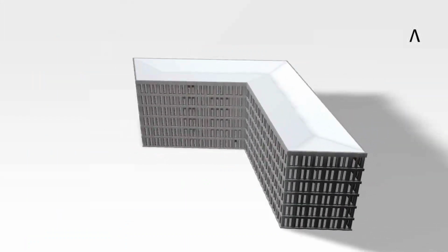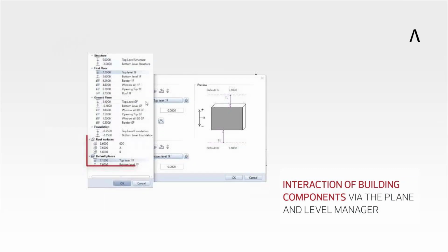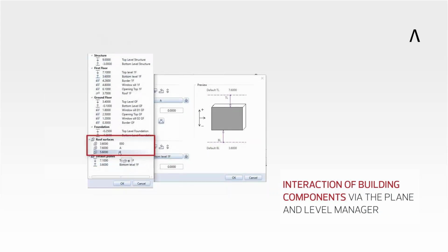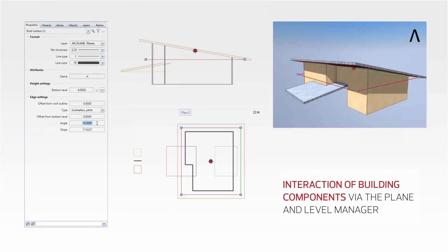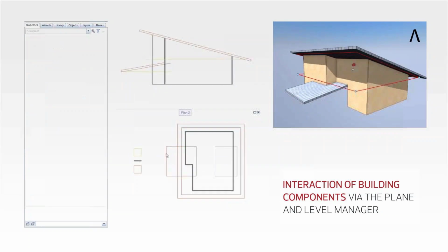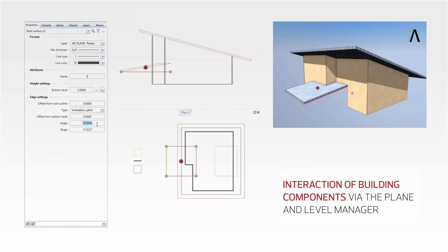And we can also have negative slopes for draining waters, and this can be also used within a floor. So it's not necessarily a rule to use it for roof, but also for floors. If we want to guide the drainage, it can be a solution with negative slopes. And it stays parametric, so you can change your mind at any time. And the advantage of working with such a roof is that if you use architectural elements, then for each roof you can make adjustments that modify the whole structure.